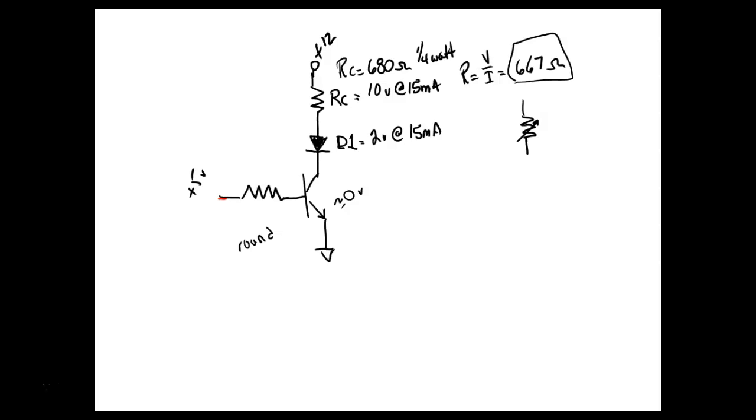Transistors have all types of ratings, but on a saturated switch, there's only a few of them that we're concerned with. First of all, what type of transistor is this? An NPN or PNP? Is the arrow pointing in or not pointing in? We don't say pointing out.